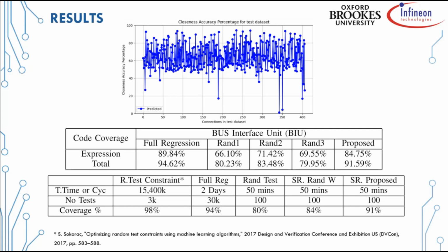In this case, it's using 15,400 K cycles, multiplied by the time each test takes to run. That's not ideal for a regression, which would take nearly a few days for that execution. Since we are focusing on regression, we are doing good results. Overall, we are getting 91% coverage with 100 tests, with an execution time of 50 minutes and another 20 minutes for the report generation.